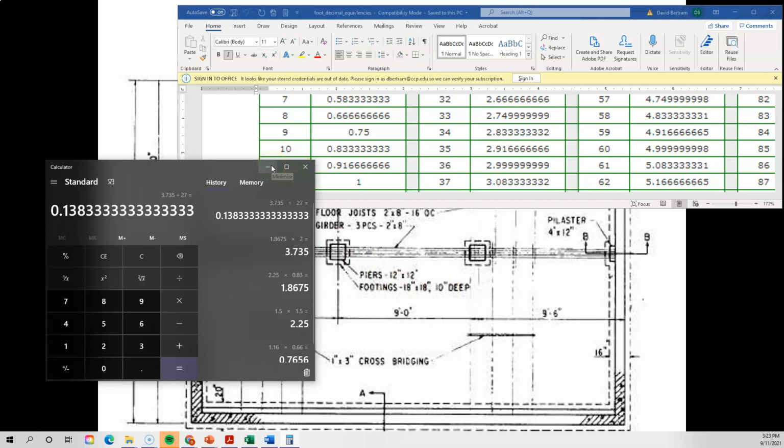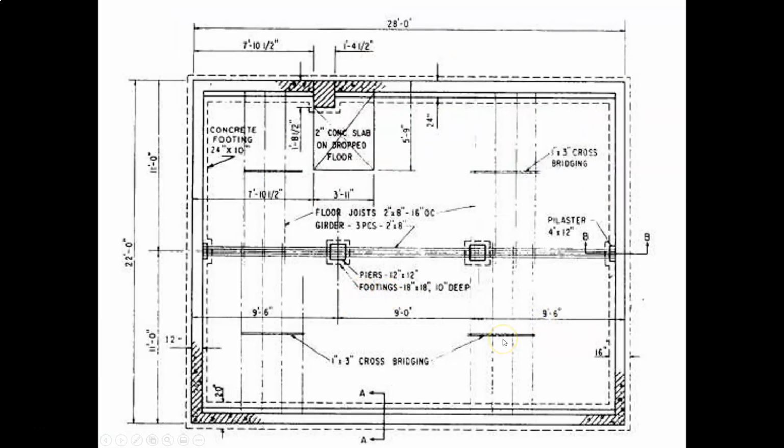Okay, and in Excel we would be very clear, and I would use the language they use. I would note that these are, I would call them, column footings. Typically I would say use the same exact language that they use, but everything is a footing, so you'd have to come up with your own name and call them column footings or pier footings. That's what I would call them, pier footings. Yeah, so use their language as much as possible. What's on your Excel spreadsheet should match what's on the plans. That's the best way.